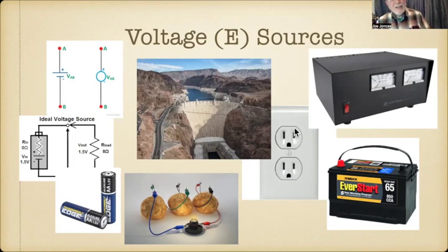Okay, let's see, does my mouse show up? Yes, it does. Here's an AC outlet, 120 volt AC, and it comes from something like this. So we take this and plug it in, which is our typical power supply for our ham station. I highly recommend this style of power supply for your station. They weigh a ton, but they put out little noise. We're going to learn about switching power supplies later. Some of them are good, some of them are really dirty and make a lot of RF noise, which gets into your radio.